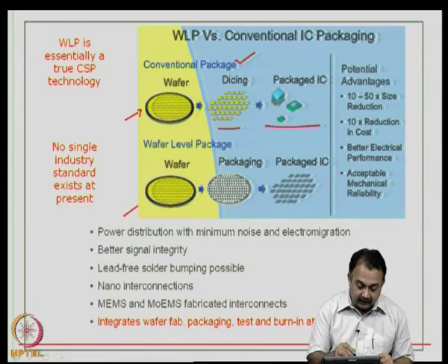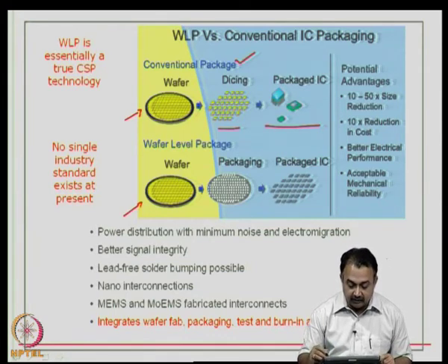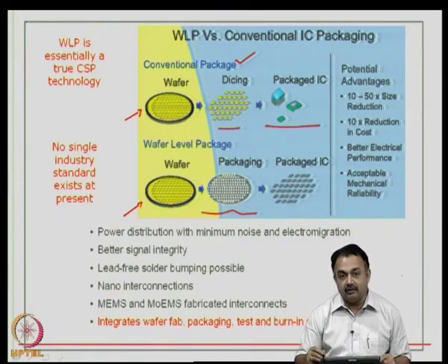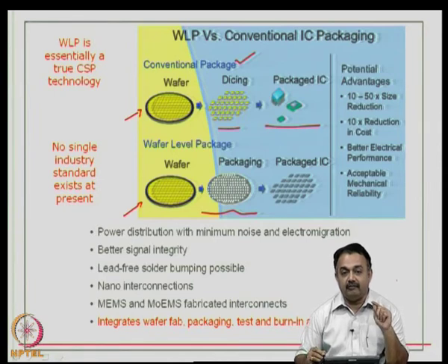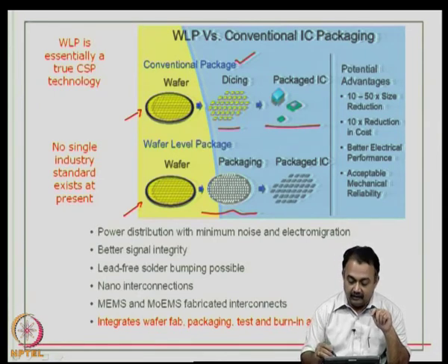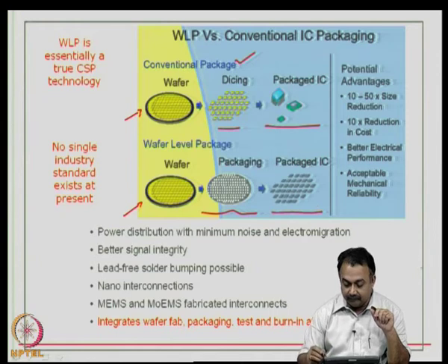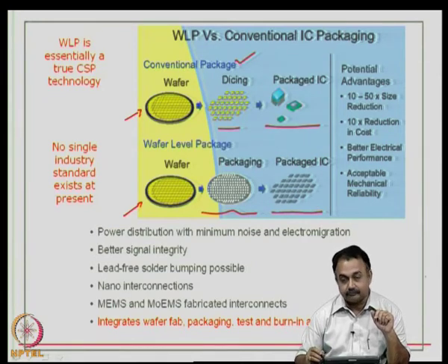But a wafer level package is slightly different. The wafer is done, the packaging is done at the wafer level. That means you are not singulating the die here, you are doing the packaging process on the wafer itself for each and every one of the qualified die and then you are singulating it.